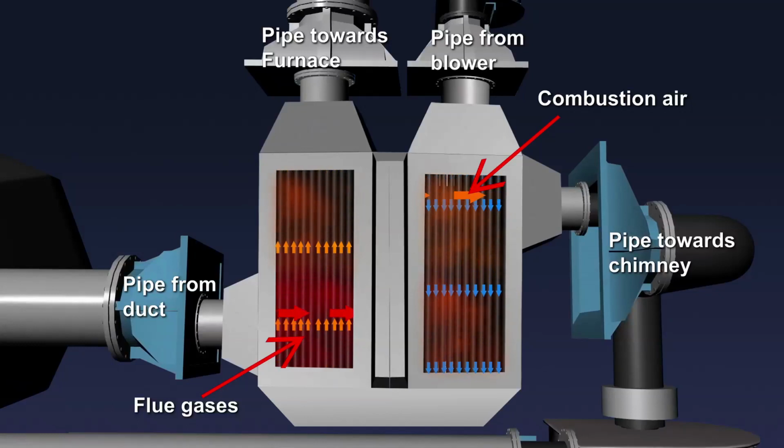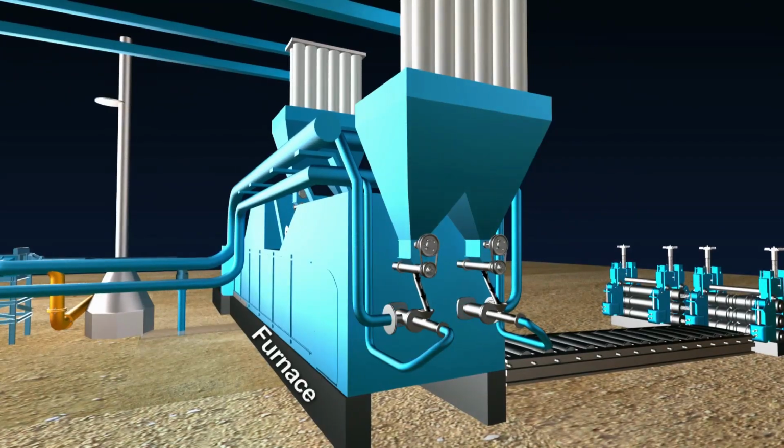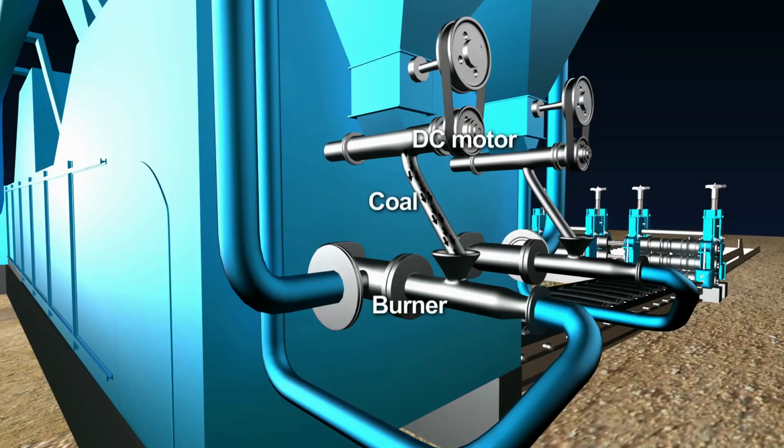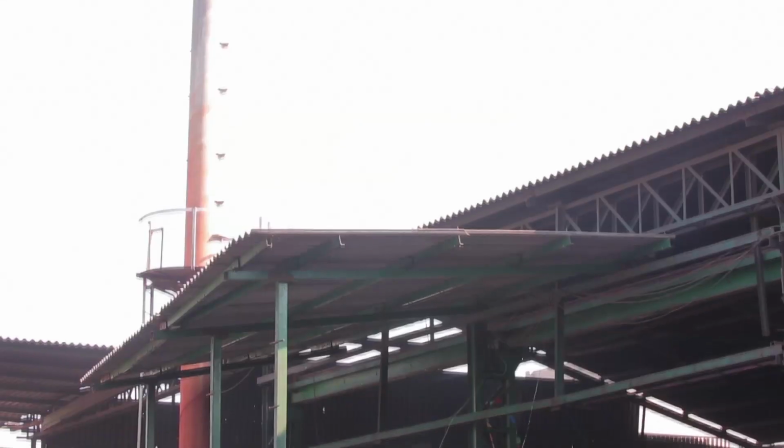The system works based on the principle of physics, which says energy moves from a hot body to a cold one. Thus, in the process, inlet combustion air from the atmosphere is preheated using waste gas. The preheated combustion air is fed directly into the burner. The result is saving in terms of fuels, increase in flame temperature, and improvement in furnace efficiency.